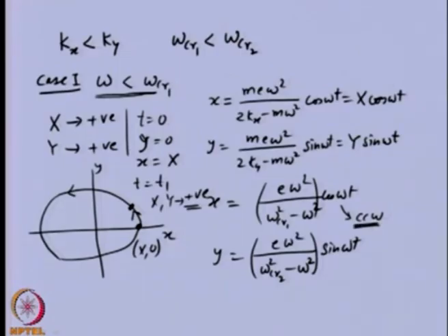Basically, here we have a rotor which is moving. This is the path of the rotor during whirling, and at time t equal to 0 it is here, and at some finite time it approaches here. So, not only is it spinning about its own axis in the counterclockwise direction, but it is also whirling.